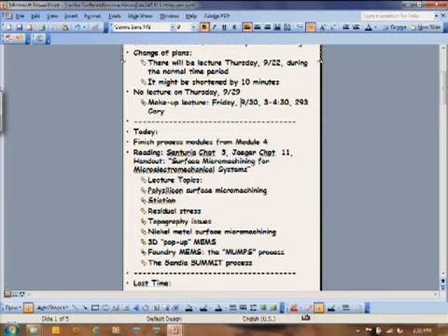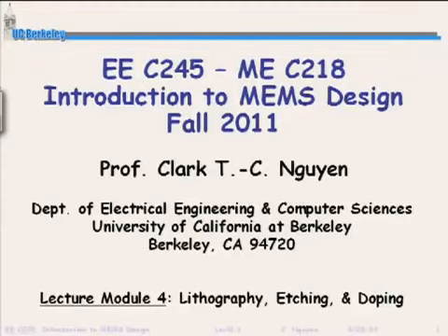So last time we were here, we were talking about plasma etching and what it was. Well, actually, reactive ion etching and what it is. I think the takeaway from plasma etching is that when you do plasma etching, you are creating a plasma, but in this plasma, the things that actually do the etching are the neutral radicals. We talked about how neutral radicals hate being neutral radicals, so they want to combine with something else to lower their energy state, which means they're very reactive. In general, in any of these plasma processes, it's these neutral radicals that do the reaction.